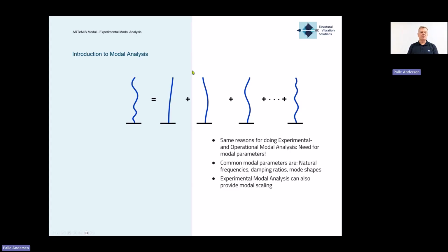So this is actually, you could say, what we are looking at in the physical domain, when we are measuring things. But what we do in modal analysis is we try to be a little systematic, and find the different building blocks that together form the dynamic performance of this structure. So what we get out of modal analysis is, first of all, a mode shape for each of the dynamic modes. There will be different ones, the first, second and third order modes and so on.